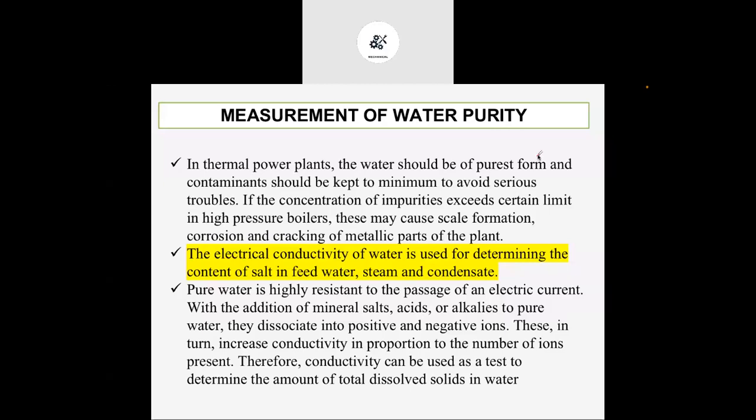If the dissolved salt amount in the water is more, the scale formation is more, and the quantity of salt precipitated inside these tubes is very high. So we require frequent maintenance, and it also affects the performance and the life of the power plant or that particular device.